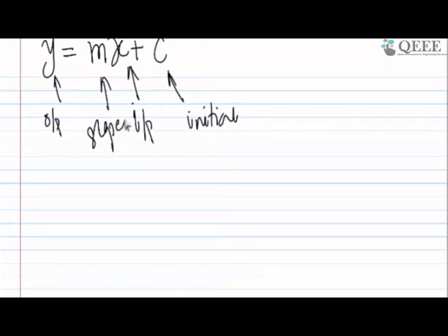If we want to mimic this equation for our case, then what will happen? This is my output voltage, this is my input voltage, and this is my common mode voltage. I am keeping it with the subscript CM. If I add one more I, it denotes that I am talking about the input common mode voltage, and the slope is the gain. So this is going to happen, and you can write the equation for your case also.